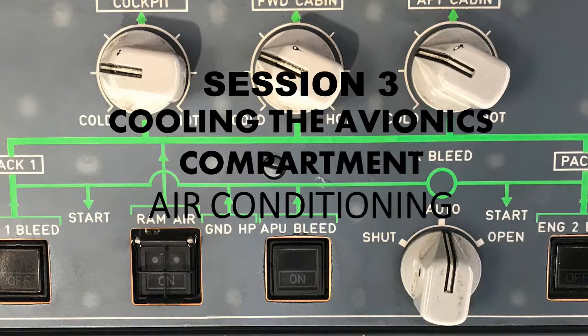And that's going to give a warning message of vent blower fault on the display. And then there's one pressure switch that, if it's detecting decreasing pressure or airflow, is going to send that signal again to the ventilation computer, and the warning message is vent extract fault. Okay, that'll show up there. So what happens at that time? What's the pilot going to do?